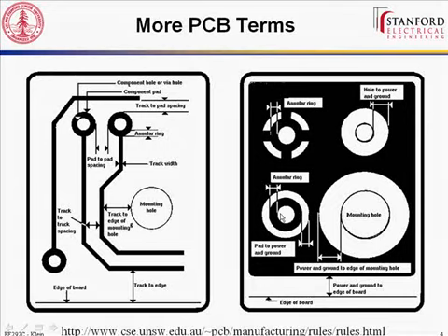So the boards are actually fabricated by imaging out your copper traces, your copper layers, and then they laminate all the layers together, and then they plate the inside of all of the holes with copper. And for the plating process to work, you have to have copper nearby. And so you're required to have this annular ring near all of your vias and all of your component holes, whether or not there's an electrical connection on that layer.